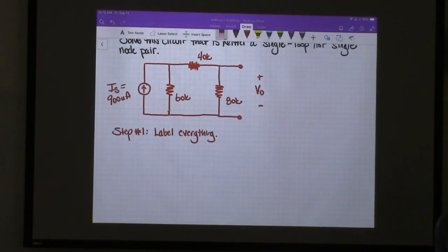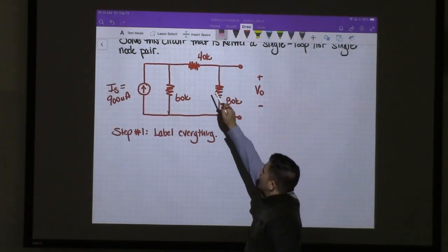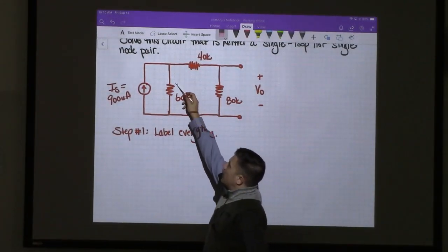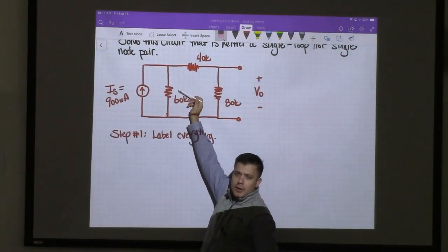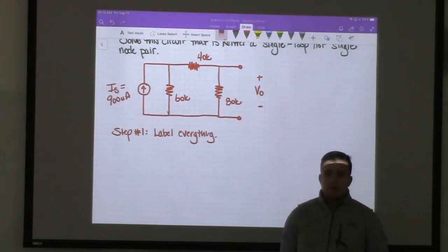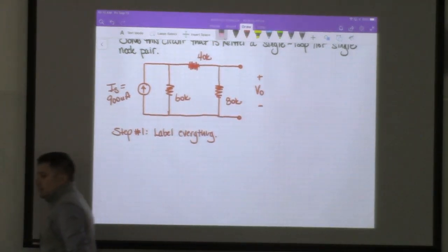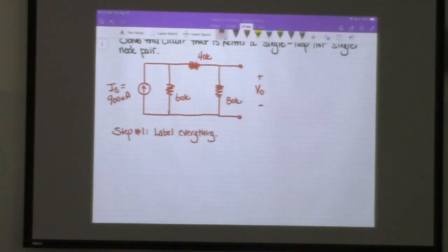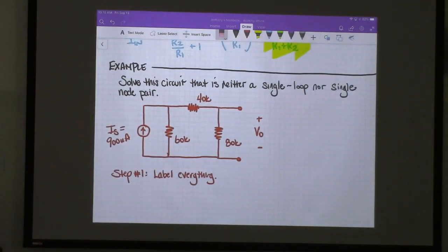We know that V out will be equal to 80 over 40 plus 80 times whatever the voltage is at the input to the voltage divider, which is the voltage right there. It doesn't necessarily have to be a source. We just have to know what the input voltage is. So right there, we went through all the steps of how to solve this problem. And all that's left is to actually go and do it.